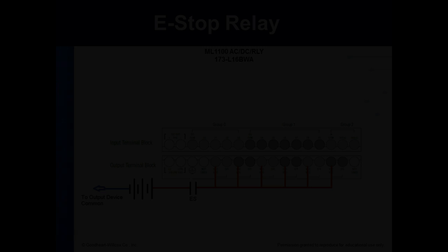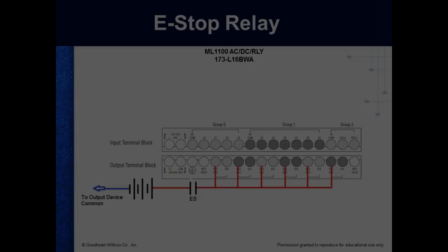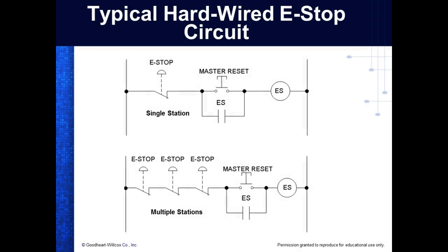Yeah, this diagram right here, this is ES, this is DS. I call it DS. Most people call it MCR, a master control relay, but the reason I didn't call it MCR is that's what the book calls their master control reset, right? Are we okay? So this would just allow us to put multiple e-stop buttons.